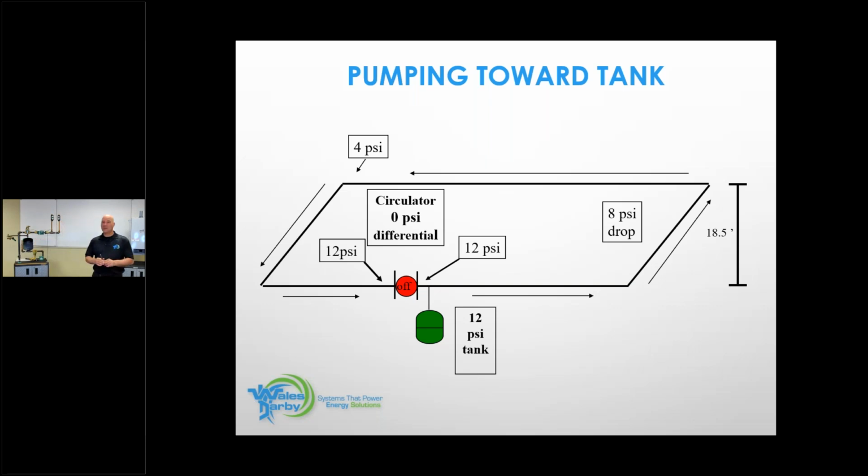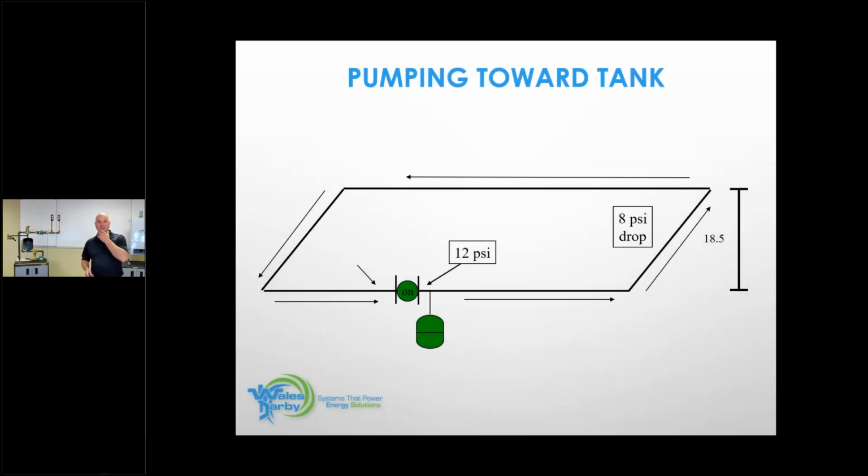So a couple of answers coming in. Nothing changes. Okay. Whoa, things jumped around a bit. Number 2 same, number 3 same, number 4 down. Okay. 12 PSI after the pump should not change, because that is the point of no pressure change. All right, good. That gentleman's been here a few times, so you should know it by now.